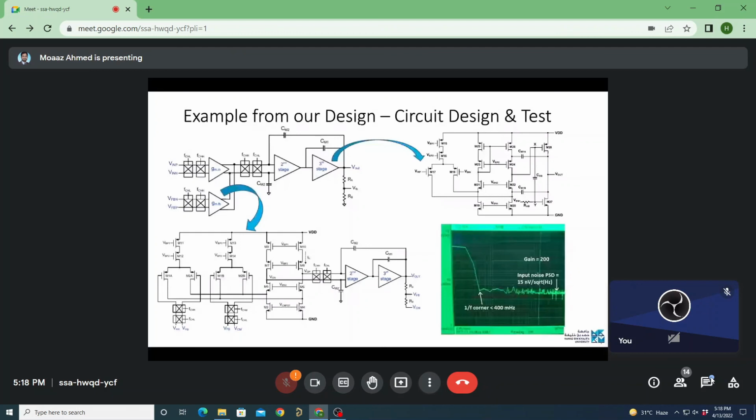So this is one of the very few published designs which have nanovolt offsets. In this design, we observed our nanovolt offset by using 2 sets of choppers, at the input and the output of the feedback and input transconductors.